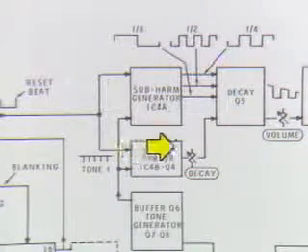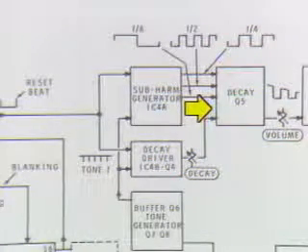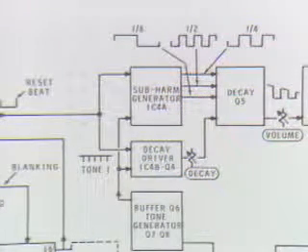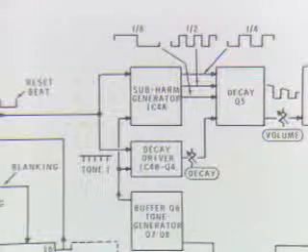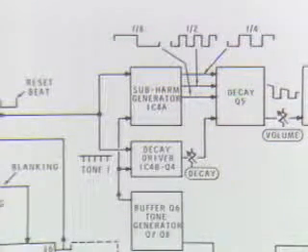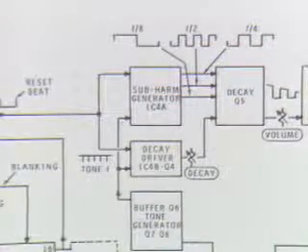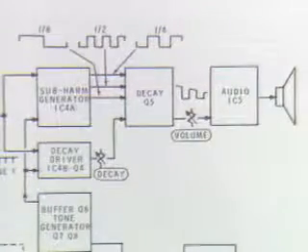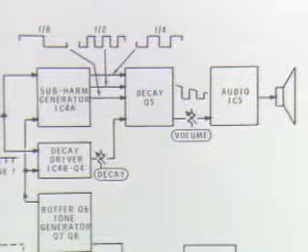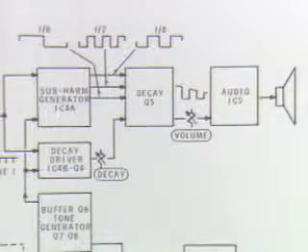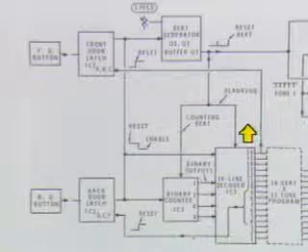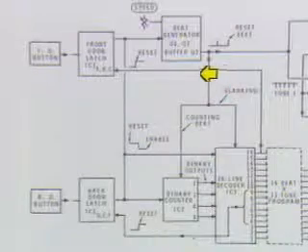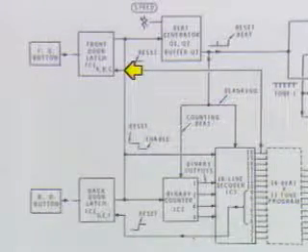The decay circuit Q5 is operating in its linear region as an analog device. This decay circuit causes the output to decrease during each beat, producing a natural-sounding musical tone rather than a clipped computer tone. This signal then drives audio amplifier IC5, an analog device, the output of which is then routed to the speaker. At the end of the 16 outputs of the decoder, a reset signal is activated and the latching circuit and the beat generator shut off.